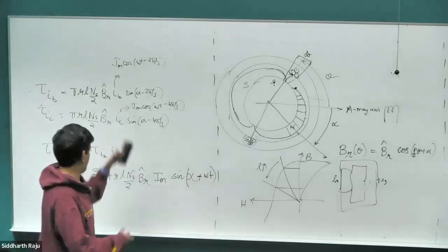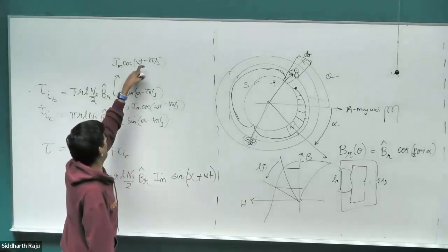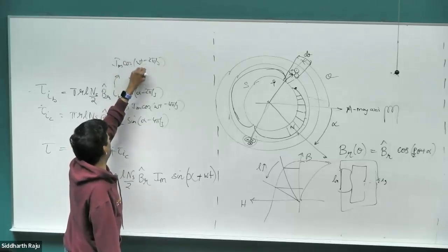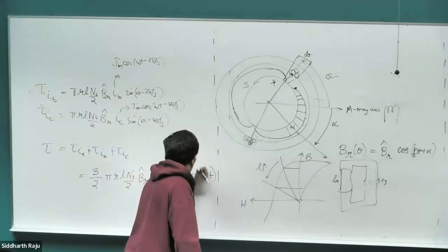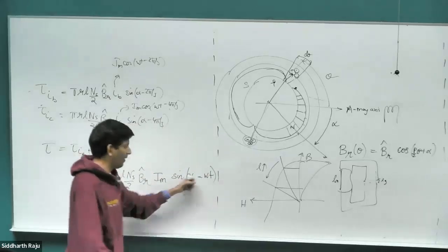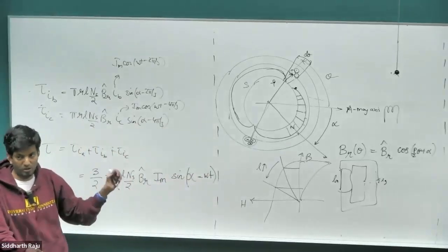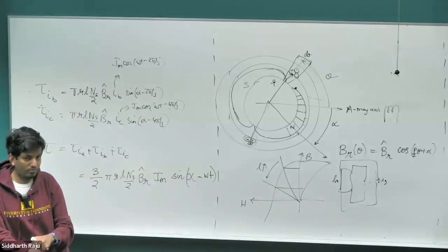So the way we derive these expressions, you add it. If I flip this current, let me make it simple for you. If I flip this to plus 2 pi by 3 and make this plus 4 pi by 3, that would basically reverse the angle of rotation. What will be the constraint for alpha so that the torque is non-zero?